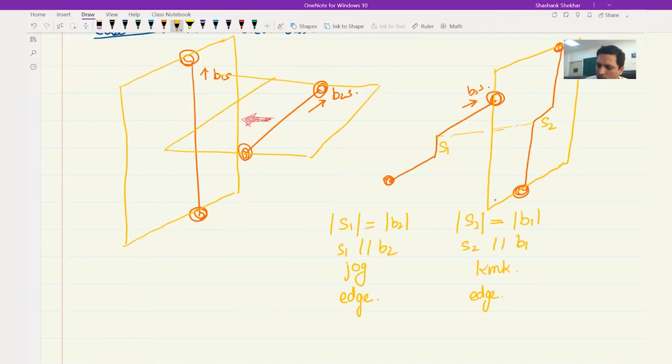So in this case, for a screw dislocation, whenever there will be a step, it will always be edge dislocation. And like I said, this is in the same plane, so this can move, and hence it can allow this dislocation to move. Therefore, it aids in movement, but this one is sessile.